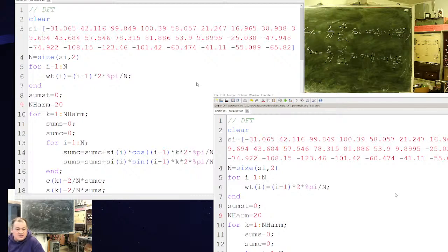Why is it a failure? Because 20 samples is not enough to maintain the Nyquist frequency. The result is distortion. If I check 19, it works. You see, it works. If I take, for example, 22, oops, everything is ruined. Because I didn't obey the rule of the Nyquist frequency.